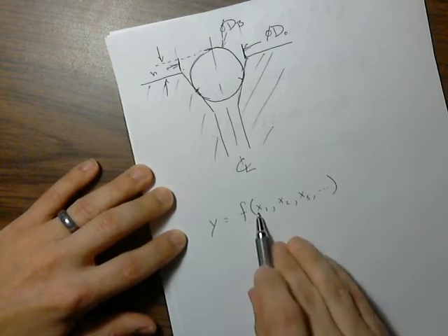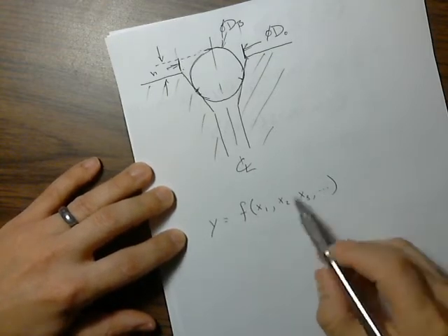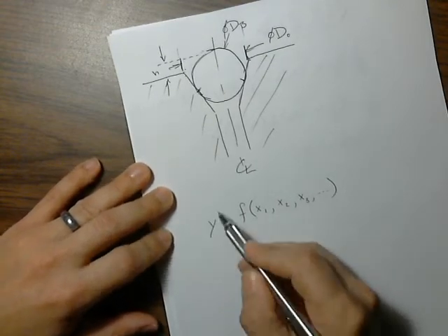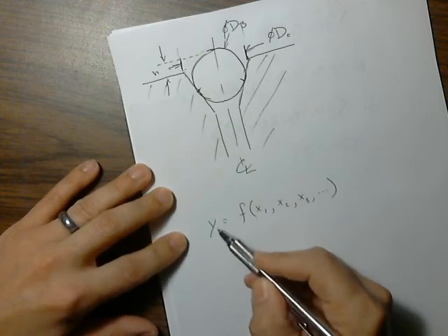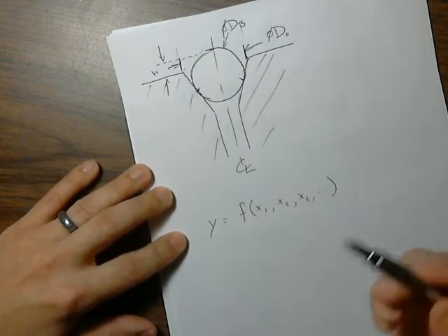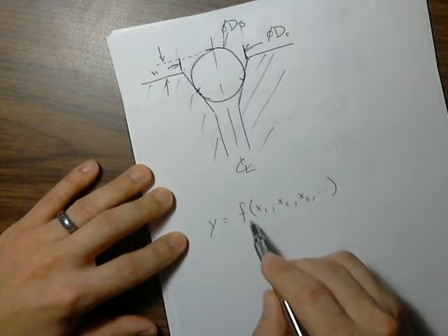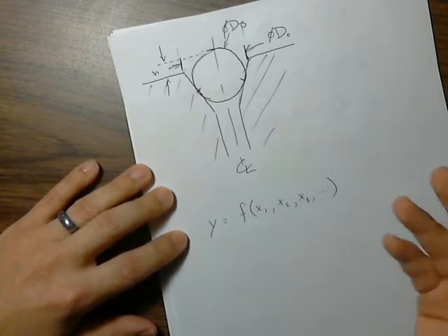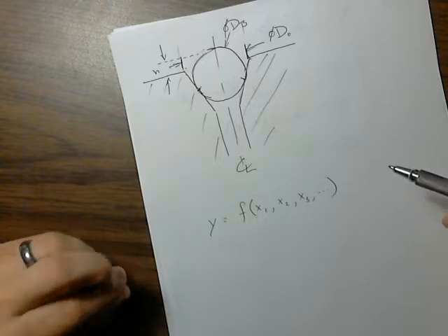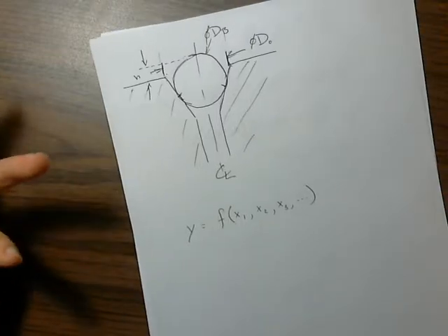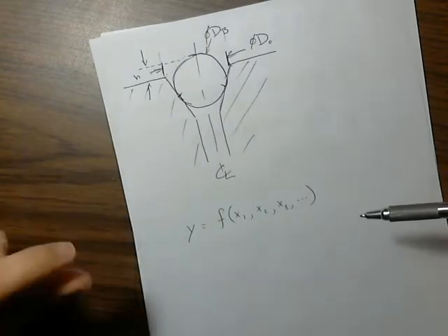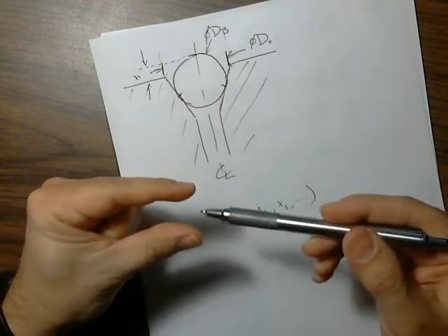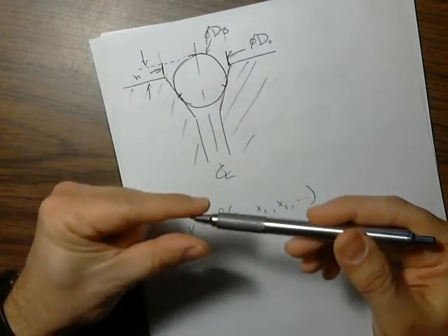So the idea is you might have to take, I don't know, a dozen direct measurements, and then from that you will calculate something that you care very much about. In other words, another great example of that would be humidity sensors. One of the really common ones is capacitance: you have two plates and you measure the capacitance of the air between them.